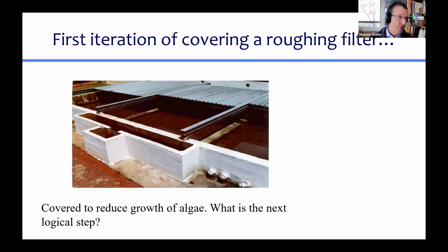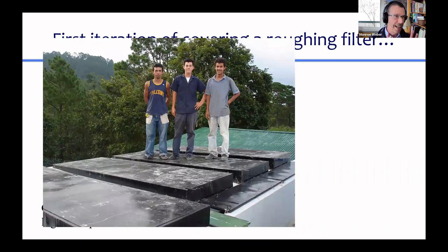So now we just laughed at these guys, right? Because they forgot to raise the roof. But we can also laugh at Agua Clara, because this was the very first plant that Agua Clara built. And we also ran into the difficulty of the sun causing damage in the plant. And so there are now 4 little roofs covering little tanks in this plant. And that means that in order to get access, and in order for the operator to see what's happening in any of these tanks, they have to lift the cover off. So this is an illustration of the roof being absolutely necessary, and a roof should go where a roof should go, which is up over your head, so that you can still see what's happening in the plant.